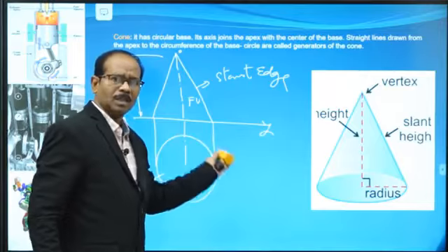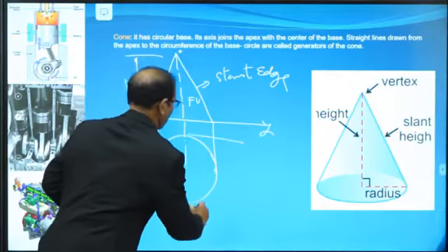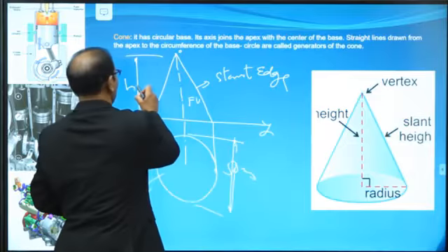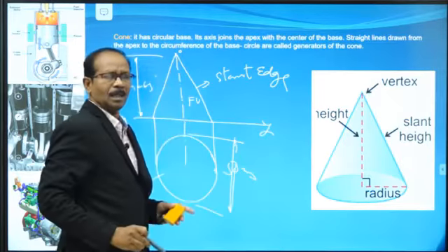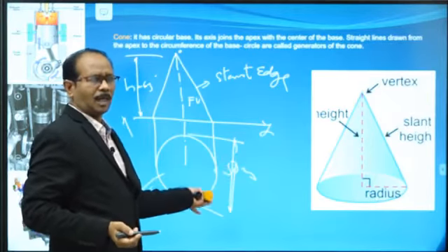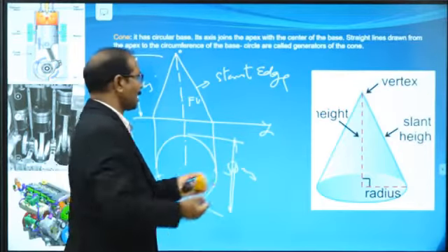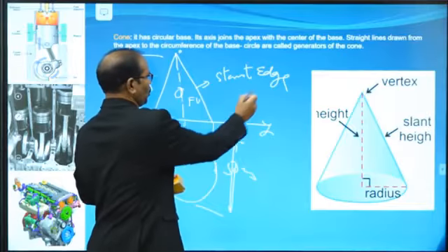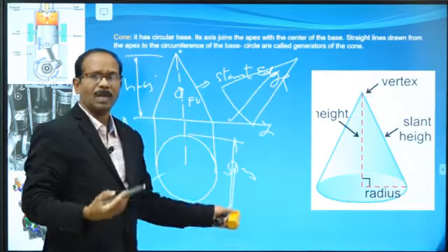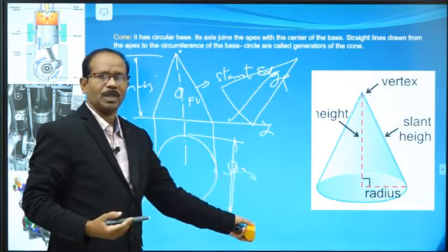Only what changes are possible in this problem? Change the value of the diameter, say 50 mm diameter, and height, say 65 mm. Then draw the projections of a cylinder of 50 mm diameter and 65 mm height, with the axis at an angle. This axis needs to be tilted in the second stage. That type of problems we have in the problem sheet.